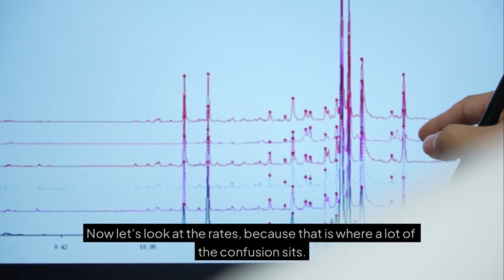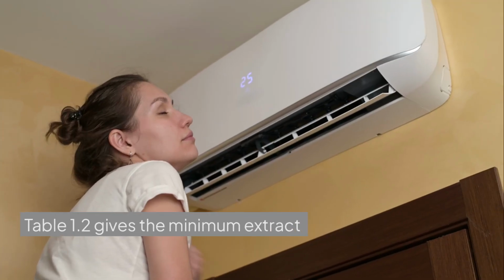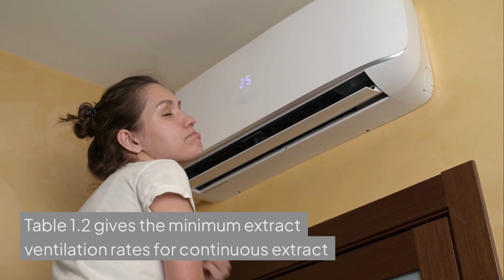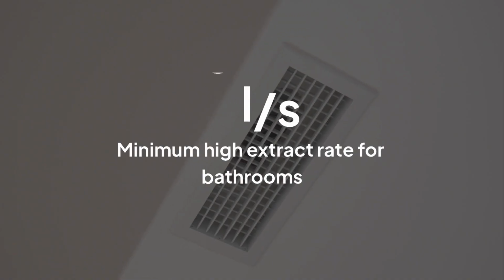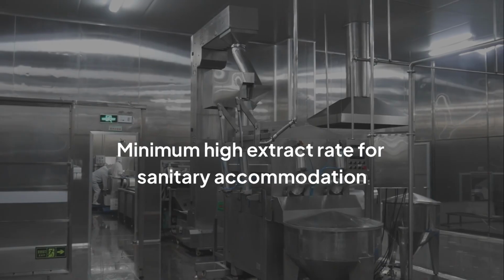Now let's look at the rates, because that is where a lot of the confusion sits. Table 1.2 gives the minimum extract ventilation rates for continuous extract systems. The minimum high rates are: kitchen equals 13 liters per second, utility room equals 8 liters per second, bathroom equals 8 liters per second, sanitary accommodation equals 6 liters per second.